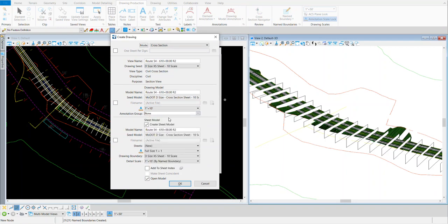And when you do that, you just hit the pull down. You go to cross sections, drawing, and in here we're going to do the one with the grid. Access annotation with grid. We've got 4 options here. We have one without grid. Some people like it with no grid at all. We have one with a major grid only. A lot of people like that option. But the width grid gives you our major and minors. And then there's one for the end area volume that we'll talk about in another video. So we'll pick the width grid.